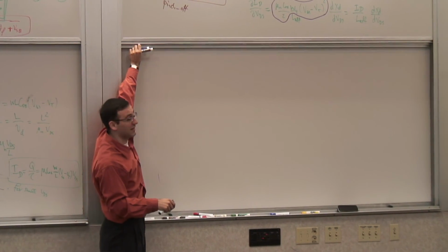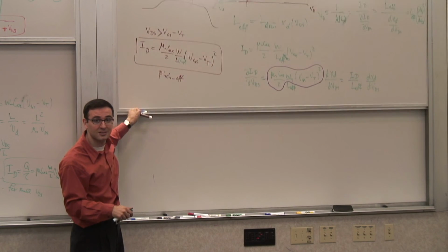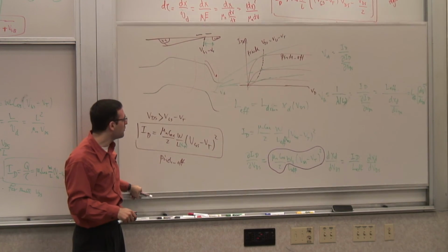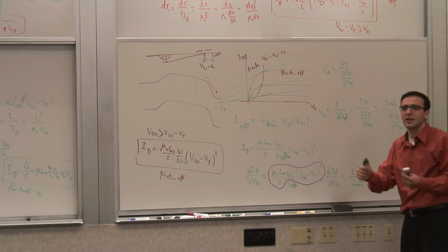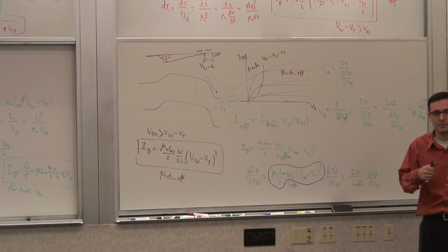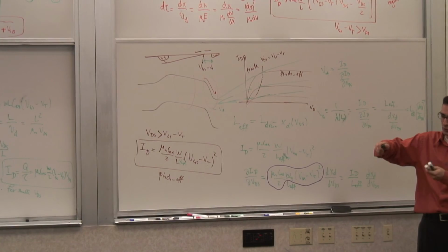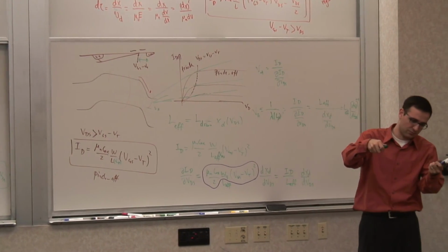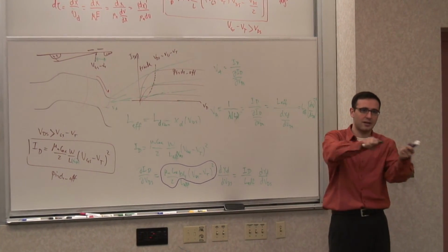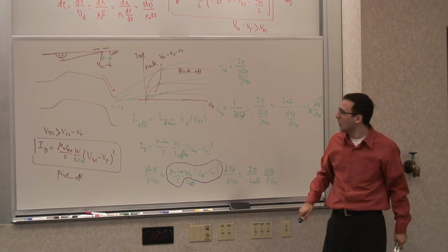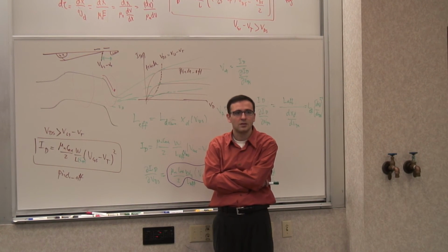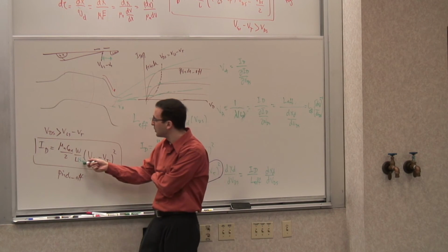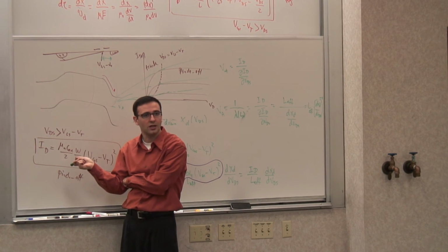Well, the short answer is, it depends on what you're trying to achieve. But what do you pay? What is the price you pay for this? There are always trade-offs, right? We'll see this very often in design: if you do this, it will affect that one; I'm going to improve this property and degrade that. So what does it degrade if I increase my channel length? The current per voltage, right?